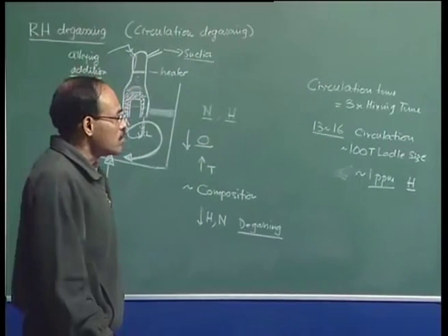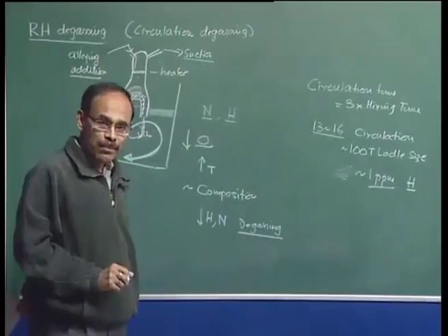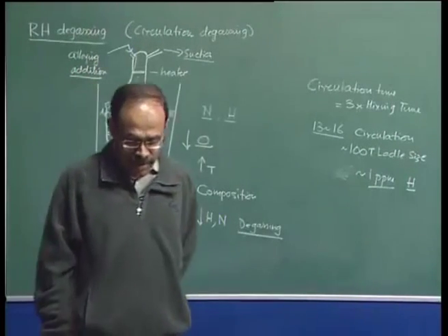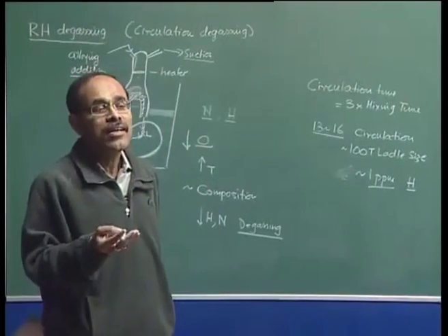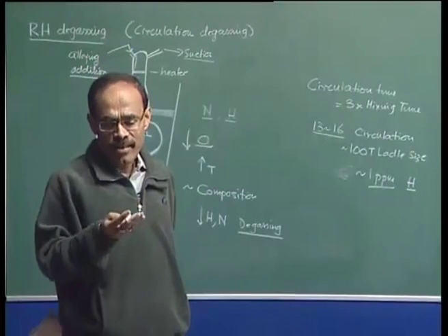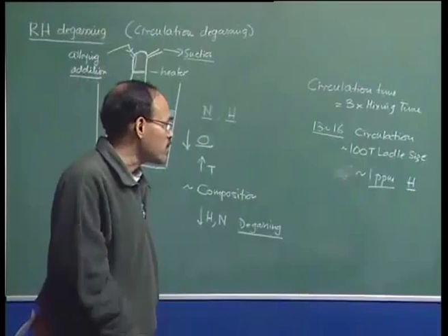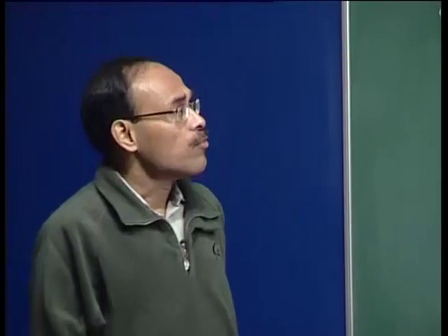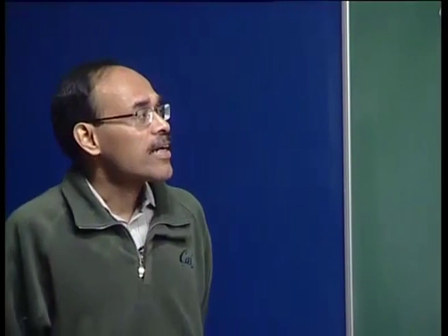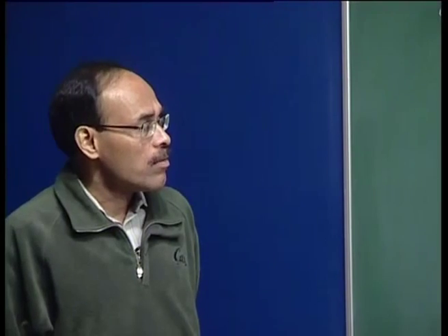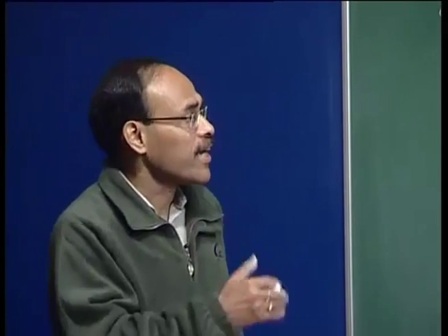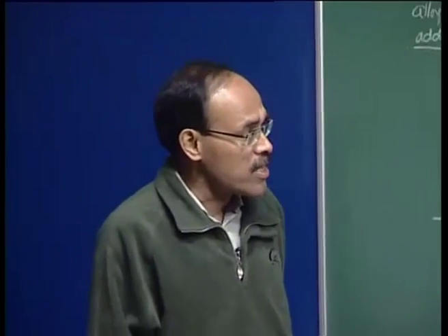Desulfurization: we all know that the blast furnace is the ideal place for removal of sulfur, because the blast furnace provides us with a relatively basic slag. It has extremely low oxygen potential, a highly reducing environment, and also a relatively high temperature, which are thermodynamically correct for desulfurization.